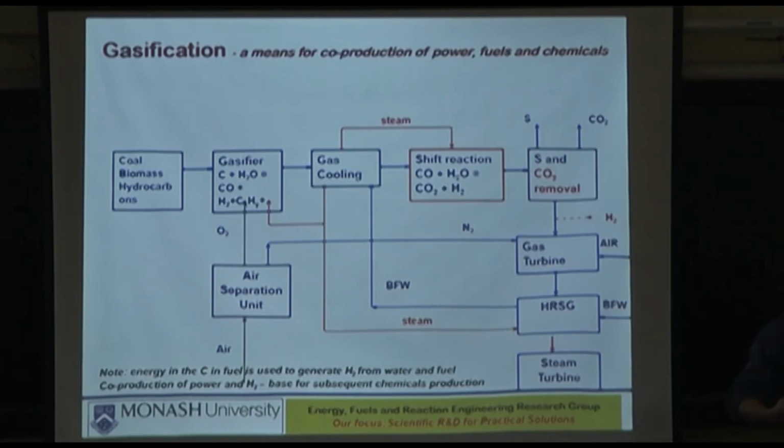To break the bond in water molecule to hydrogen and then oxygen, you need energy. That energy will come from where? From here, from this carbon, essentially. And that carbon has come in the form of CO from the gasifier. You are giving extraneous water steam here, and that's giving you the hydrogen. So, coal gasification giving hydrogen, actually yes, only to some extent. The majority of the hydrogen comes from the shift reactor.